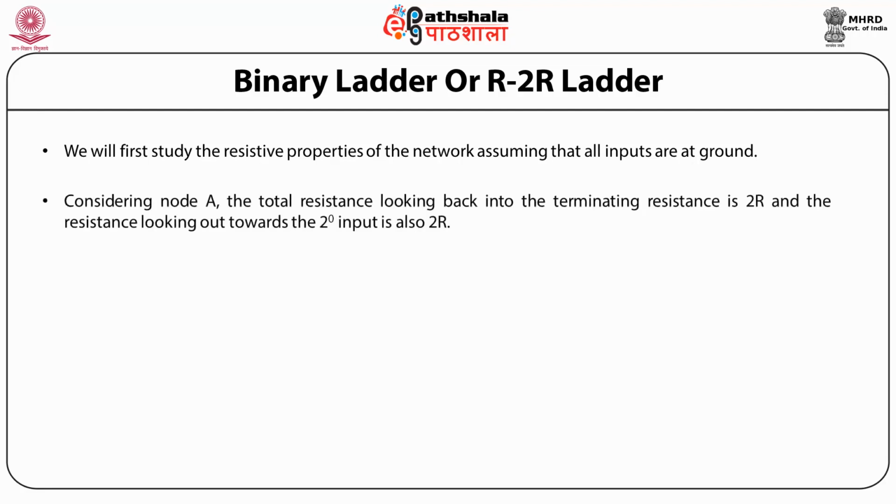Considering node A, the total resistance looking back into the terminating resistor is 2R, and the resistance looking out towards the 2^0 input is also 2R.